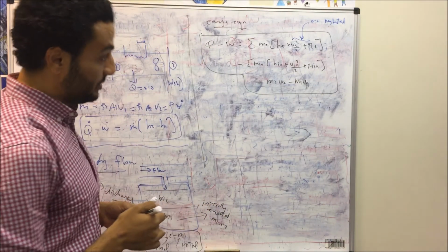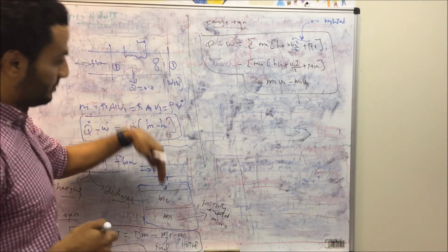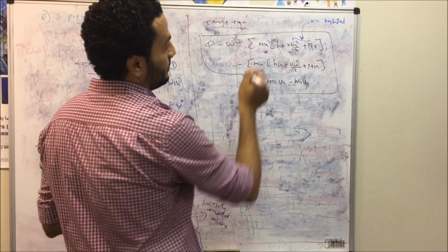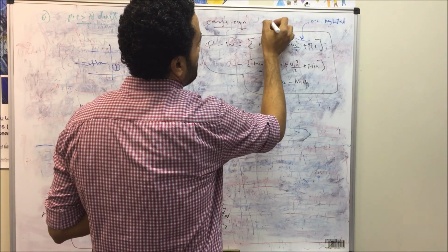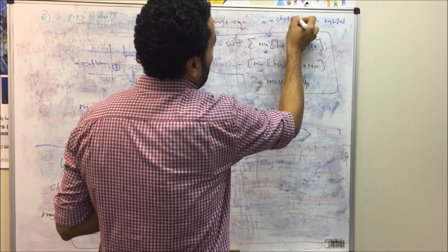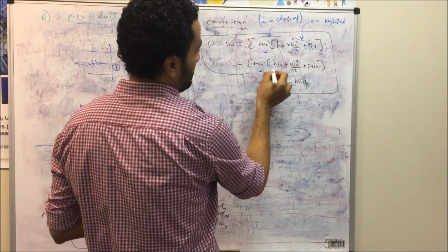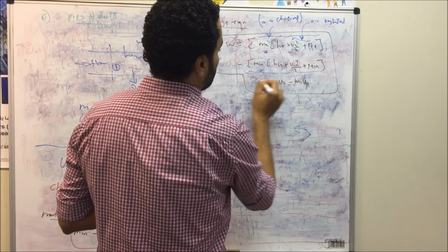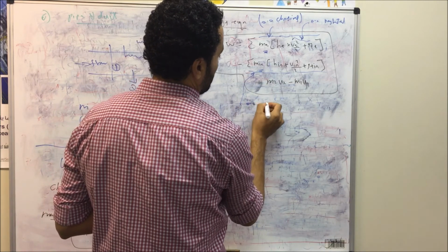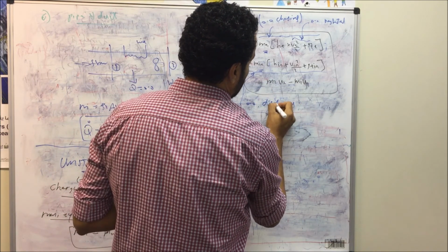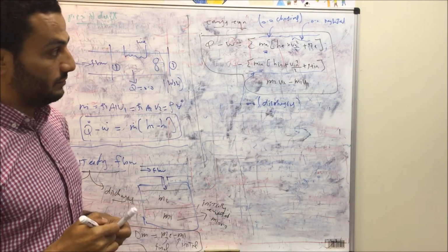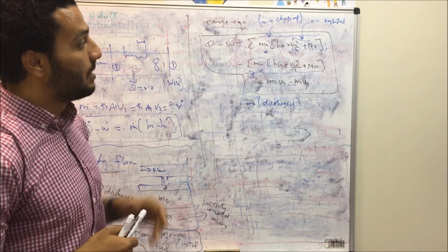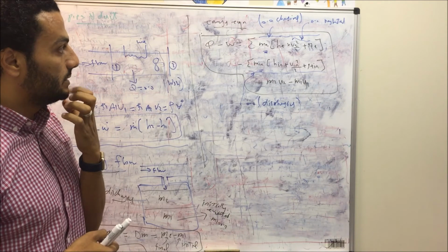Either discharging or charging. Now in case we have charging, or filling a tank, we have mass in, but in this case this term will be 0. So this term is 0 in case we have a charging process. The whole other term will also be 0 when we have a discharging process. A tank discharging flow has mass out but no mass in. A tank being filled has mass in but no mass out, so either of those two terms will be neglected in those cases.